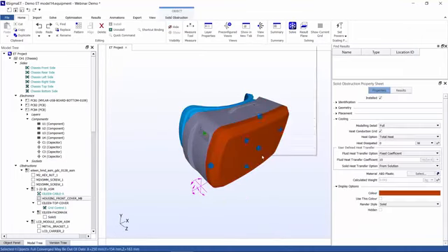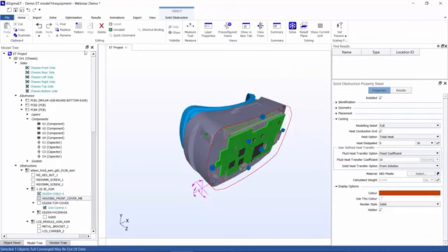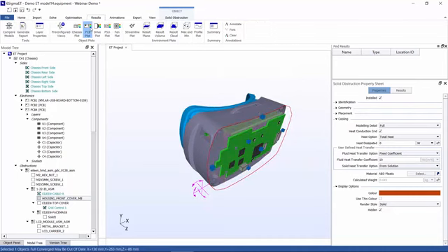And now I will hide this front cover. And I'll show our pre-configured view. So with a couple of clicks, we can quickly look at important values such as our mean surface temperature on our components. And so this really allows you to quickly get through the model and see what's important and what's going on. Finally, I want to talk about result planes.